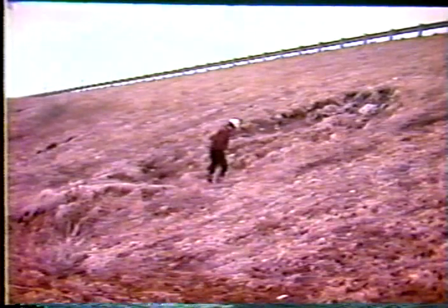Another example where a buttress could be used, here again this particular slide looks like a shallow failure because the upper scarp there, if you notice, is sloping quite a bit. It looks like sort of like a mud flow, which you could come in and excavate part of that out and replace it with rock. Here again, you're going to place the rock against a geotextile, which was placed against the excavated slope.